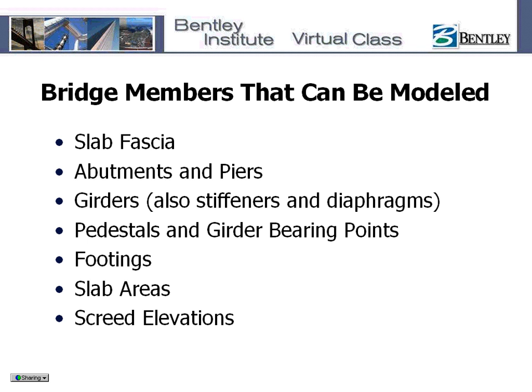Also, you will lay out on the substructure the pedestals and girder bearing points, bearing pads. You can also lay out geometries representing the footings and also create geometries representing the slab areas. And again, you can report on all the elevations, screed elevations, clearances, and we'll be doing a little bit of that today.